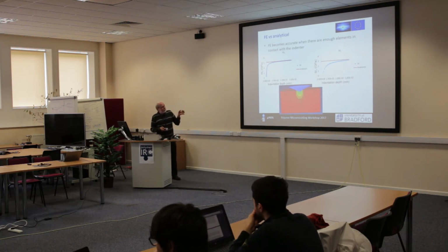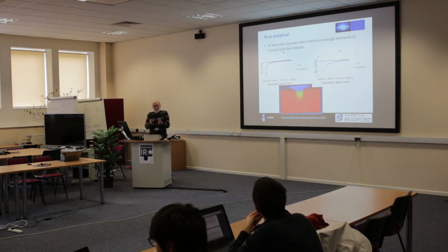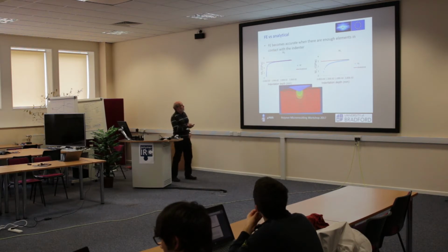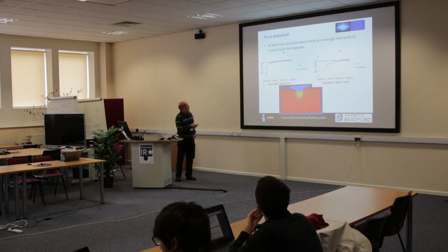And as you proceed, of course, this analysis is calculating the area based on a small number of elements to start with, so it won't be very accurate. At the very start of this, you have partial contact with maybe 4 elements, and that's not going to do a very accurate calculation. But as it proceeds, it gets better, it reaches a steady state, so it's not changing much once you go to this depth. So this is actually millimeters, so my analyses are pretty unrealistic in terms of how far you penetrate it.